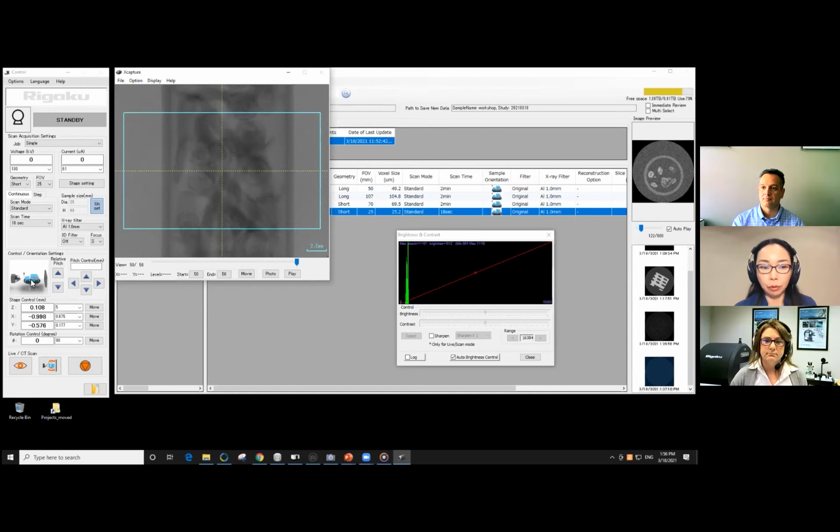So for testing a lot of samples or parts in a short amount of time, regular radiography or 2D imaging definitely makes more sense. But it's good to have a CT capability on the side. When you see a problem in the radiography testing that puzzles you and you don't know what you're looking at or what the problem is, then doing an X-ray CT scan would help resolve the problem and answer your question. So I think those are complementary. They have their own places.